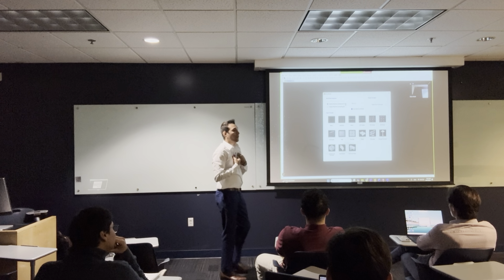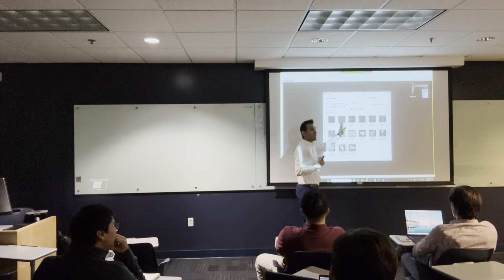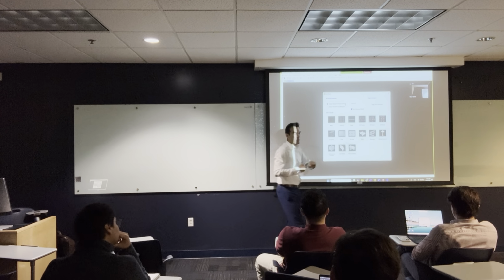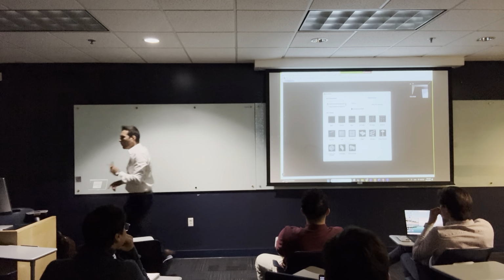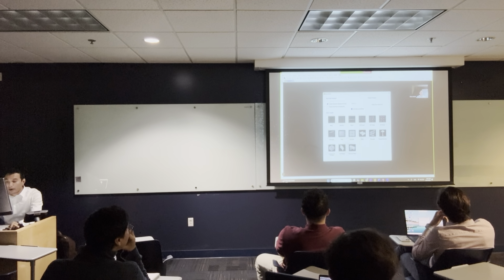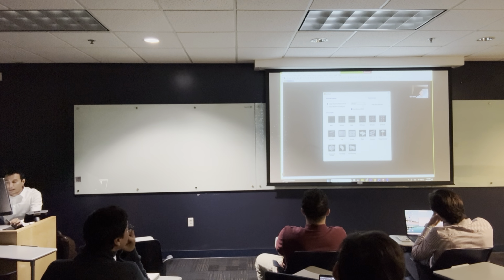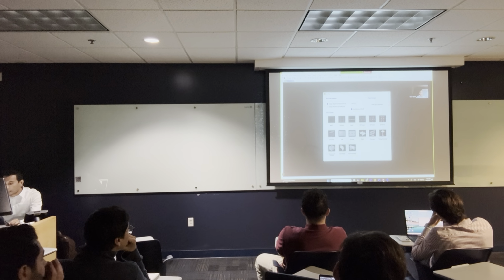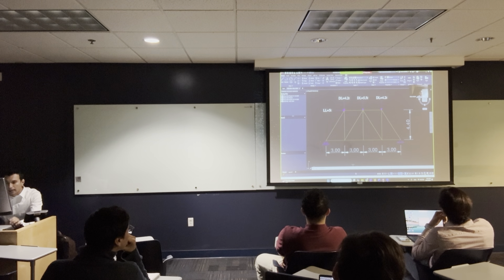Okay, so for me, I'm going to do this truss using grid only. I'm going to teach you how to use this tool. But before I do this, I have to do some stuff very quick. I have to tell SAP 2000 what units I'm going to use. I'm going to look at the AutoCAD file that I have. The distances or spaces are in meters and the loads are in tons.